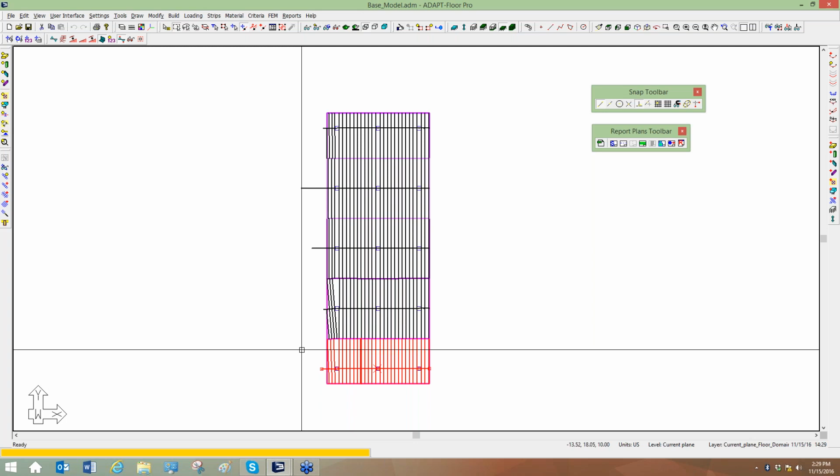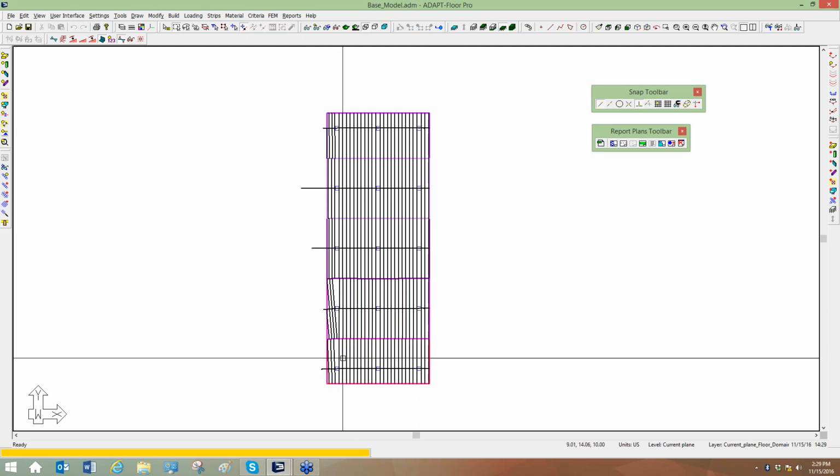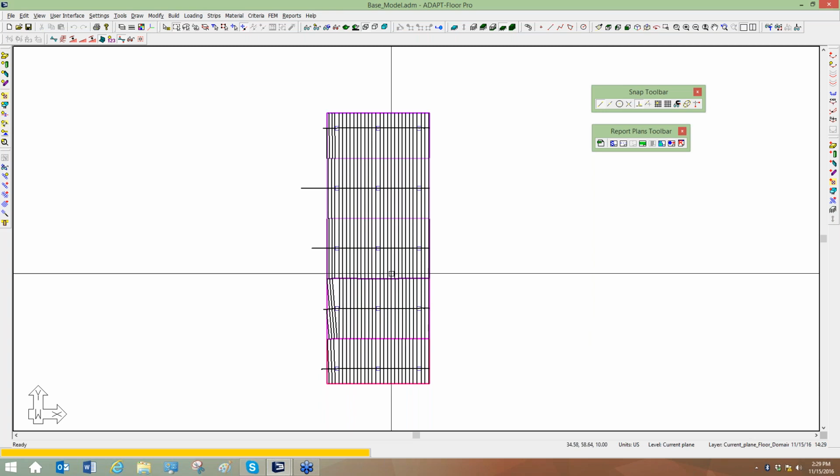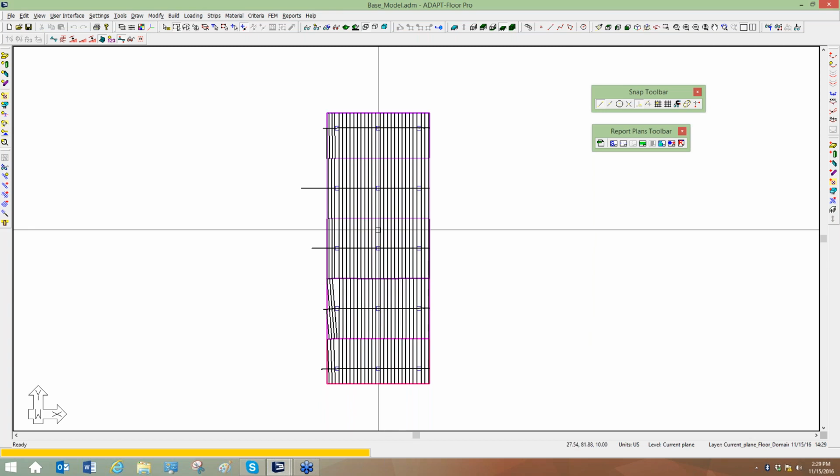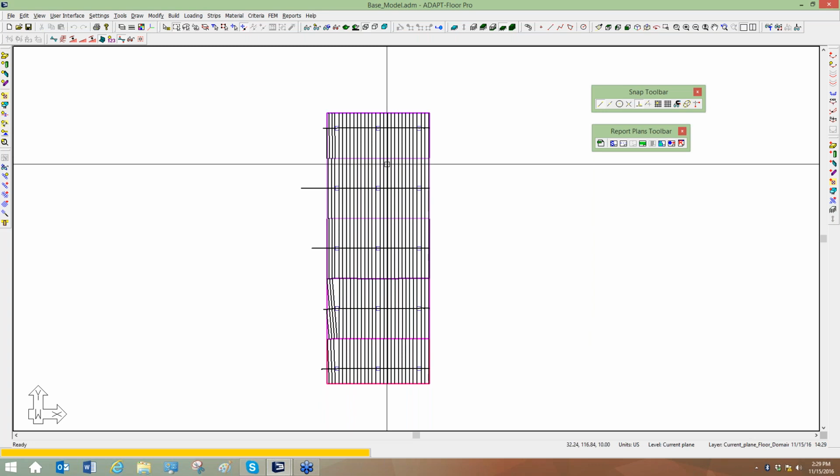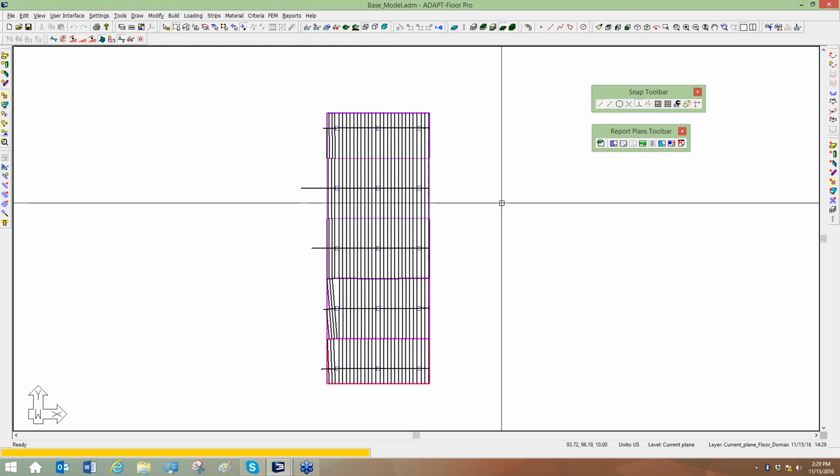And then we get our strips right here. So this is a post-tensioned slab, and you can see that the strips that we've created are really over the full tributary of each frame line. There's a side debate that you can always have whether or not it should be column strip, middle strip.